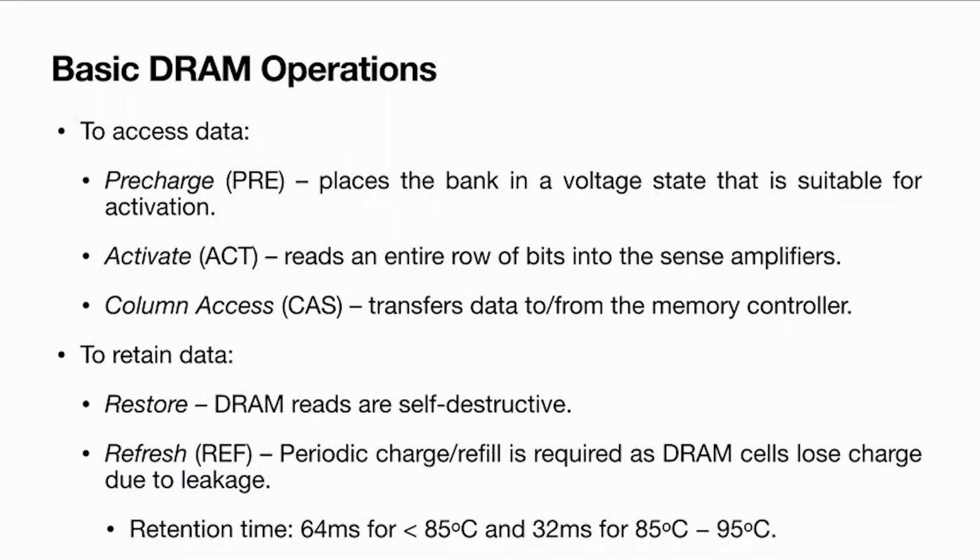But this is not only the refresh operation, there is also another operation called restore. Because as I said previously, whether it is a read operation or a write operation, first I have to read from the DRAM array and put it into the sense amplifier. Once I read something from the DRAM array, the corresponding cells lose their data. Now you have to restore it back. That is the restore operation.